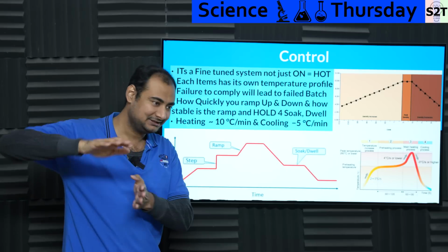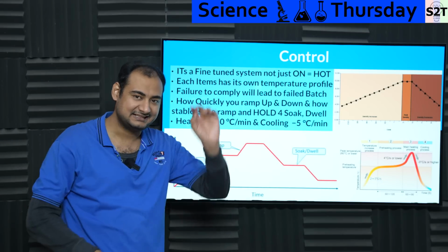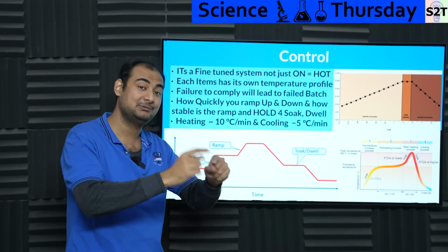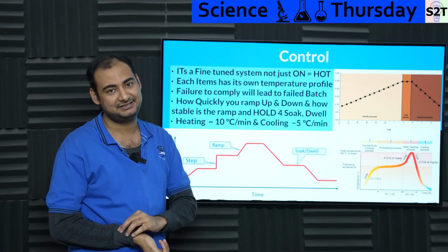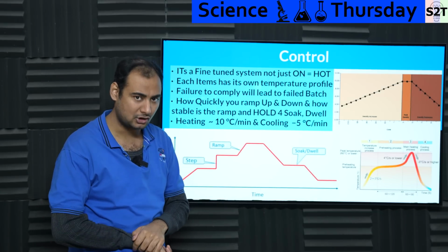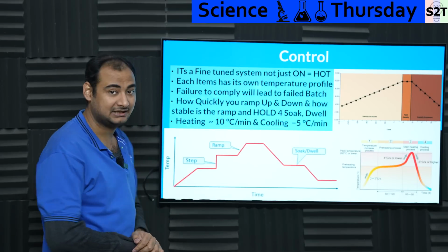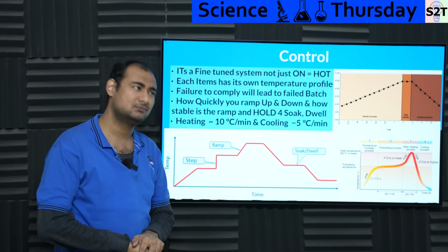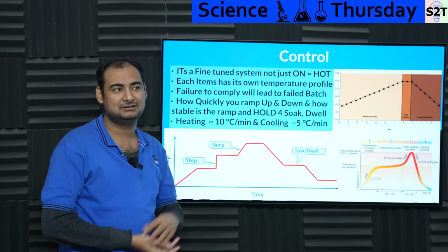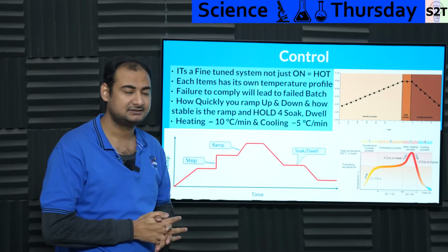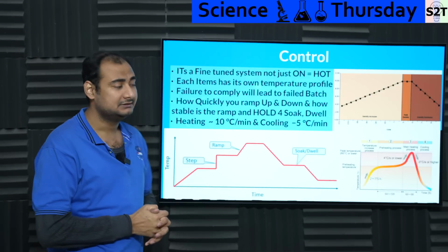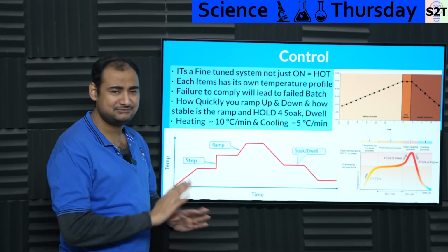So what do you do? You heat it up, then move the board into a different section. That section would be for cooling. It will be designed for cooling specifically, so you can control that minus 3 degrees per second drop effectively. And by the way, that can also be done for metals, but most of the time metals are not in a scenario where they need rapid cooling, unless you're dealing with certain alloys, certain ceramics, certain grain structures. Most of the time you do not have to worry about it.